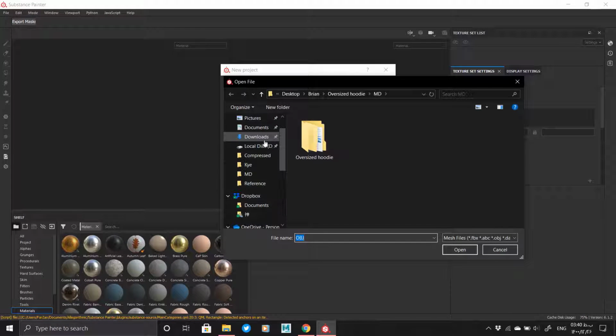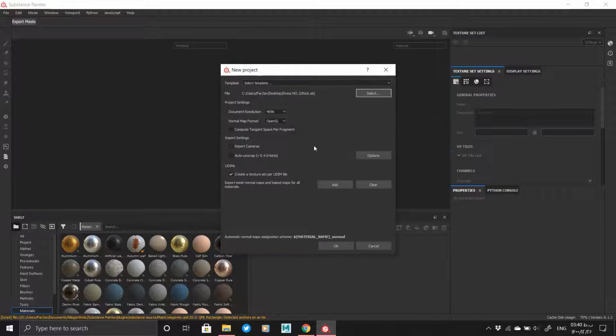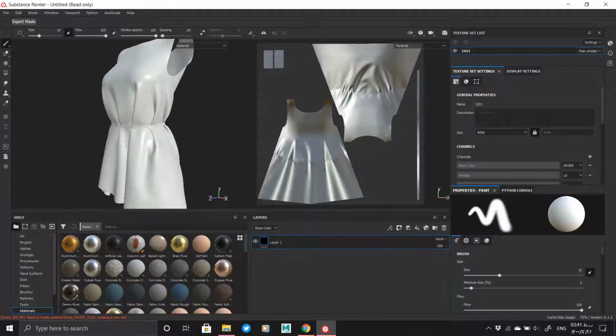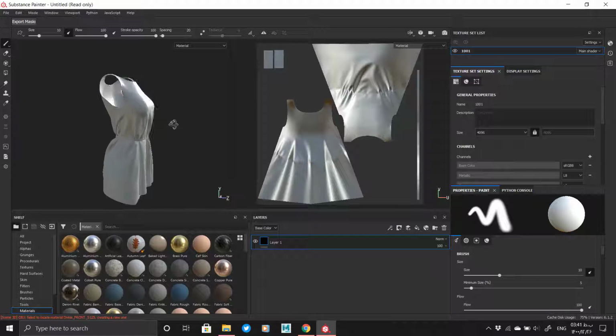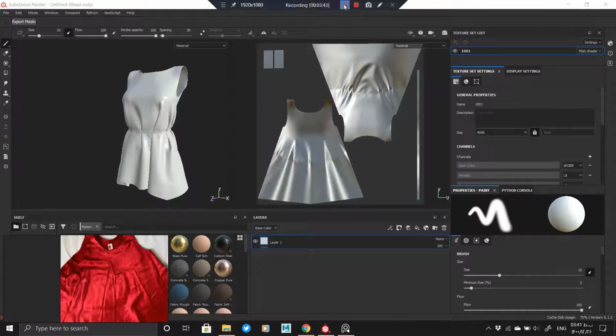Save the output as OBJ without avatars. Select the single object mode, and choose one of the 3 modes, thin weld, thin unweld, and thick, based on our needs. In thick mode, for the thick parts, the UV is not defined. So in the case of thick output, it is better to define the UV thickness separately, for other parts in that software.